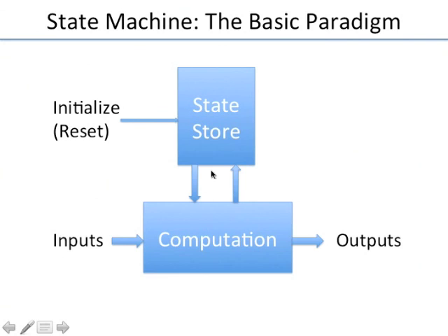And since you have finite storage, you have a finite state machine. This is also at the heart of models for computing, like the universal Turing machine, which is the basic underlying model for computing. So this is what it looks like. You have a state somewhere which you use to operate on the current input and also modify the state. When you think of it this way, your designs, everything becomes much cleaner to handle, analyze, and build.